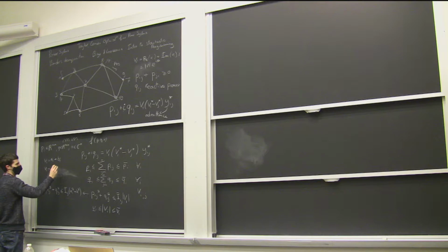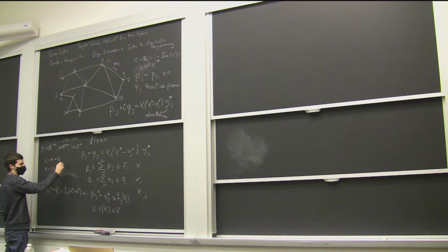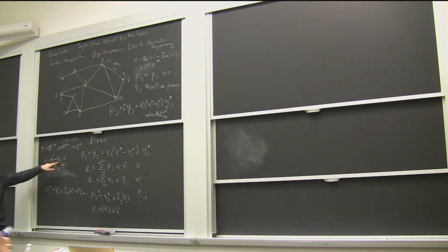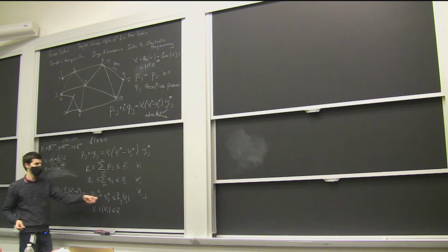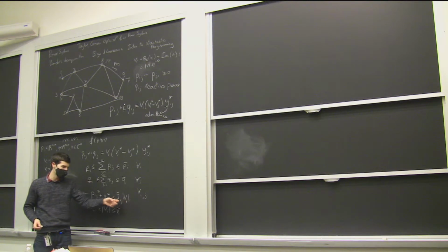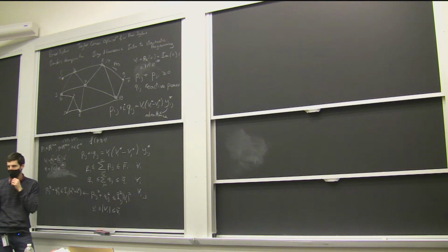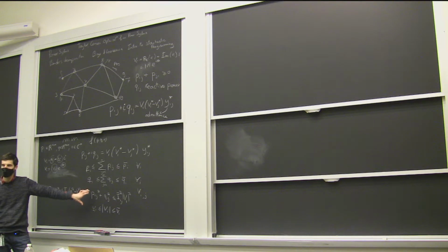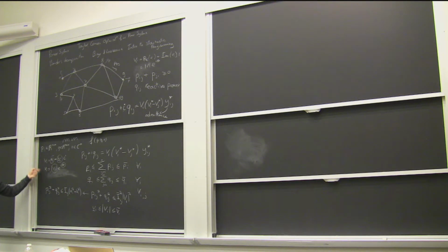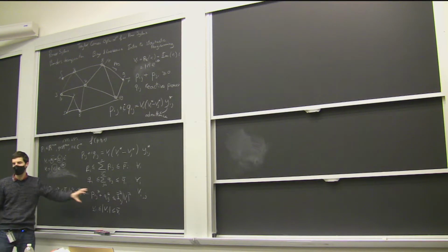Vi e to the i theta. So now the variables are theta and Vi. These are here the two real, imaginary number. Here you have two real decision variables, and this is not convex. But if you use these two real variables to parameterize Vi, then in fact this is just a real decision variable, and this is exactly, you need a square here, sorry, this is exactly second order cone. Okay, so depending on how you parameterize Vi, you will either have this as a convex constraint or not as a convex constraint.